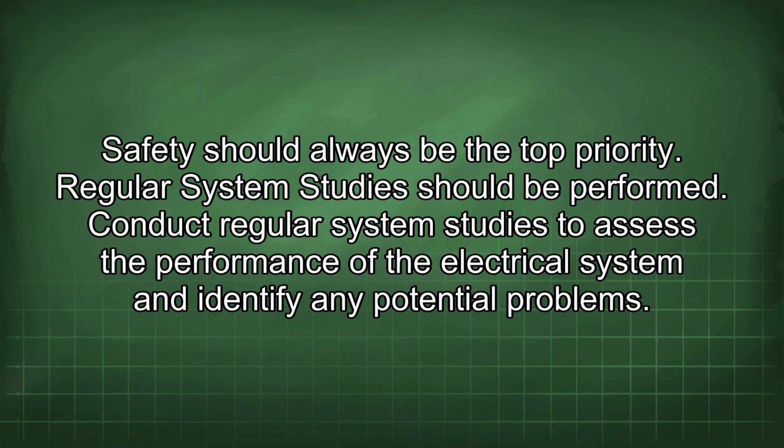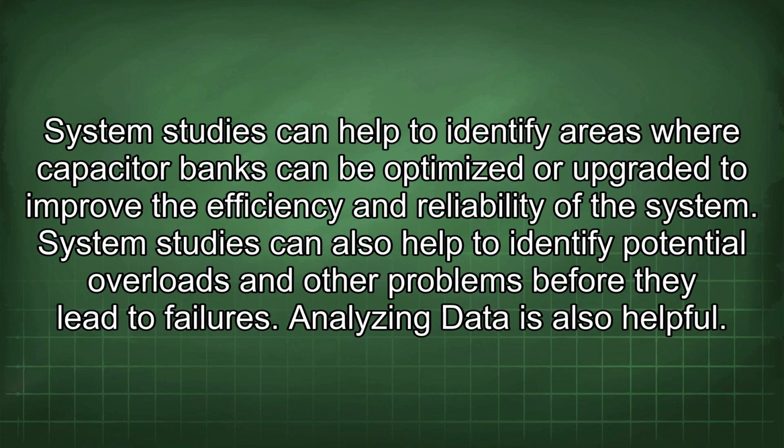Regular system studies should be performed. Conduct regular system studies to assess the performance of the electrical system and identify any potential problems. System studies can help to identify areas where capacitor banks can be optimized or upgraded to improve the efficiency and reliability of the system. System studies can also help to identify potential overloads and other problems before they lead to failures.